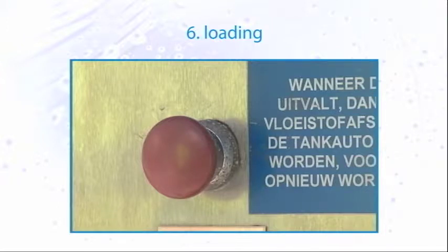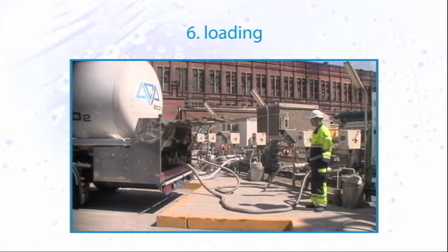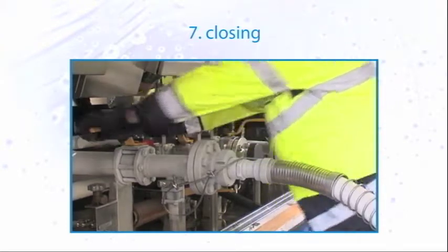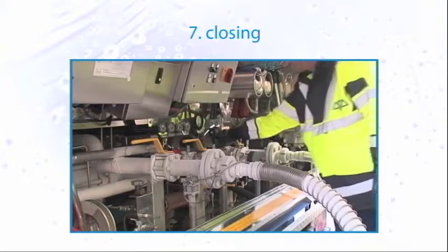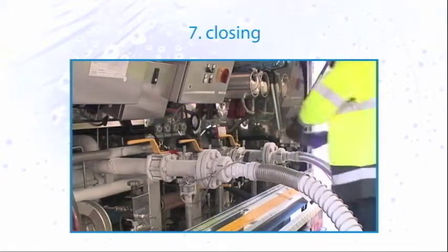If you want to interrupt the loading cycle, this is possible by pressing this stop button. To restart, press on the Start button again. During loading, always remain in the vicinity of your lorry. When loading is finished, close the gas and liquid valves on the lorry. Warning: you may never load more than the requested quantity.